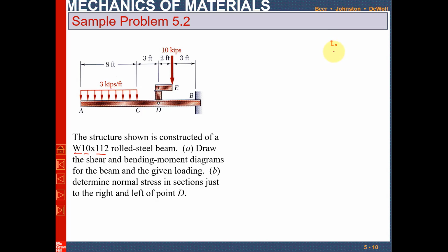You can also check the height, width and breadth of the beam, thickness of flange, etc. As we know, sigma m is equal to Mc over I. The I value can be taken from that table, and if you know the cross section of the beam, you can also calculate the C, the distance from the neutral axis to the topmost fiber. You can take this value from the table available in appendix C of rolled steel beam.